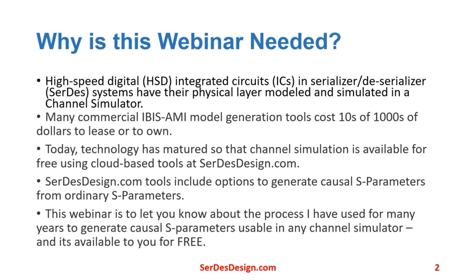Included with the SerDesDesign.com tools are options to generate IBIS-AMI models from circuit data collected from SPICE circuit simulations or from hardware measurements. This webinar is to let you know about the process I've used for many years to generate causal S-parameters usable in any channel simulator, and it's available to you for free.